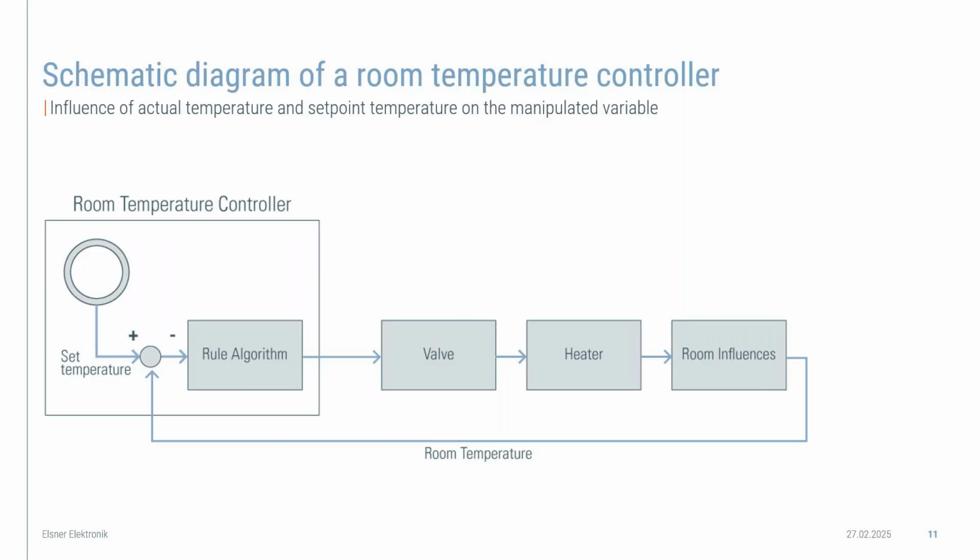So there are actually various influences on how the room temperature in the room itself can be influenced. For example, the radiant heat from lighting, if you don't have automated shading. That's actually a very neat trick to reduce the heating cost in winter, but that's another topic of its own. Next up, if you have a lot of electrical appliances like a washing machine, an oven, a heater, a dryer, this definitely will emit a lot of heat output that needs to be taken into account in individual room control.